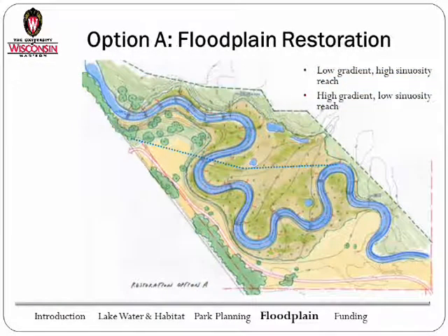This first one represents the option that follows the information we found at the reference reach. It's the same gradient, same meandering pattern. So this first reach, we're able to take that pattern to here. However, there's another 3.5-foot drop that we needed to go to, so we had to change to a steeper, less meandering stream pretty much along this stretch between these 2 dots.